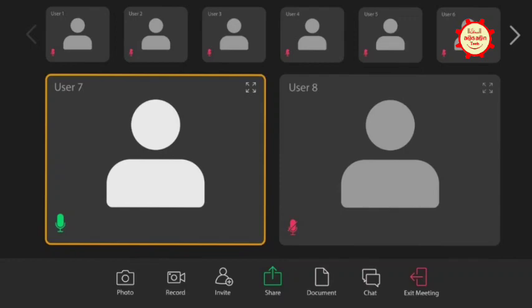Even if you mention it in the drawing, in my experience the person who is doing it makes his own judgment. When you mention that diameter, he may press more or maybe press less. So he wants only his own value to be given as the blank size. Then only he will do the right one. Whatever he says, if you give only that, he'll form that size.